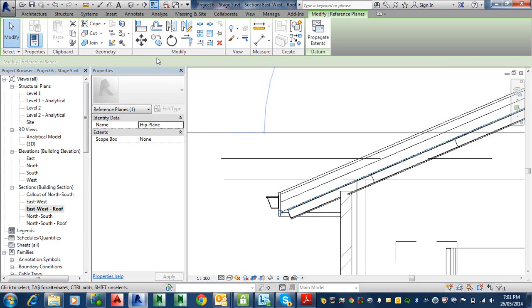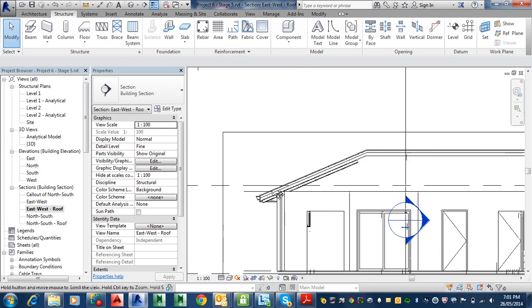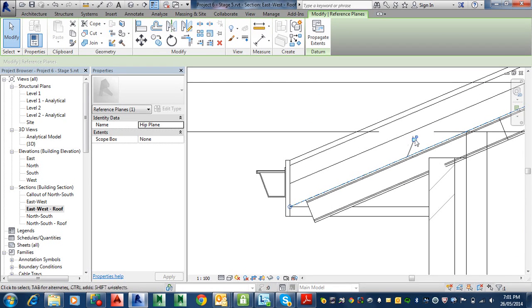Shouldn't you unlock the reference plane first? Yeah, I should have. I think I said to do that, but I didn't actually listen to my instructions. It says remove the lock symbol from the reference plane before issuing the command. So that's a bit rude to write that instruction at the last bit of the paragraph when you don't normally read that bit until the end. So, yeah, we should unlock that.